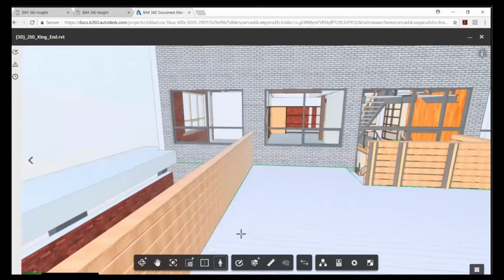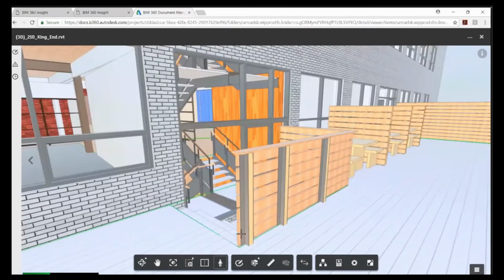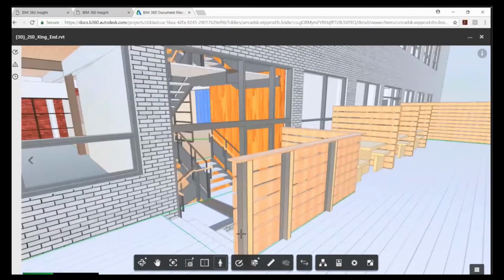And for the newest version of Recap, which is Recap 2021, you can now compare the scan view and overhead map view side by side. You can also use the compass widget to set the XY axis for the user coordinate system in the overhead view.